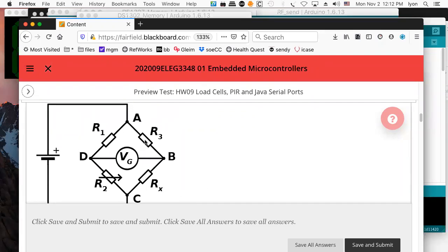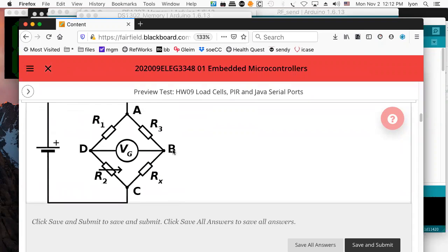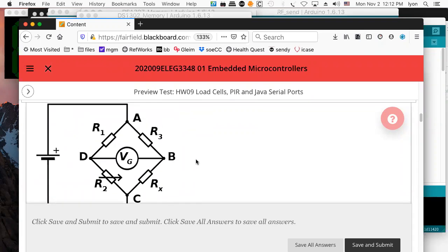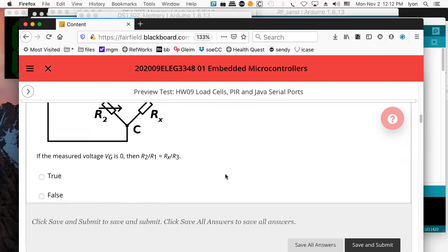The strain gauges are dotted at orthogonal points with respect to one another in the cell. And then you can measure deflection in this way. In fact, all you need is a voltmeter and a battery, and you could hook it right to those load cells. You don't actually need an HX711 chip or even a microcontroller. You can do the whole thing with a galvanometer.